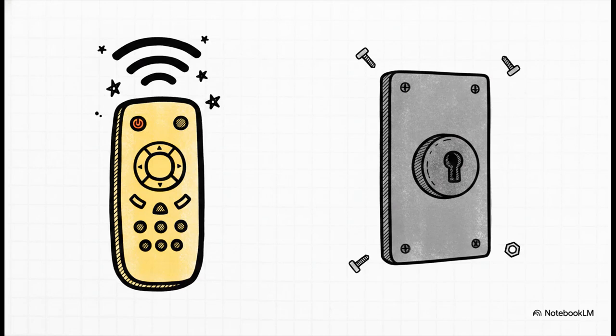To make this super easy to remember, think of low impedance REF like a universal remote. It uses numerical algorithms right inside the relay to compensate for mismatched equipment using software. Super adaptable. High impedance REF, on the other hand, is like a fixed key deadbolt. It absolutely demands that all your hardware matches exactly, and it requires those external resistors. It's way less flexible, but man, once it's set up correctly, it is rock solid and virtually unbeatable.